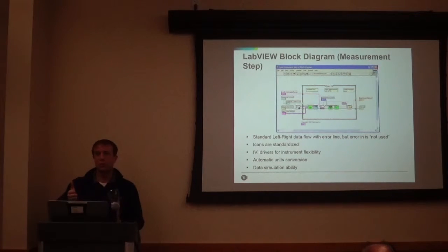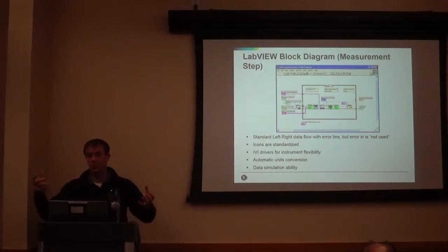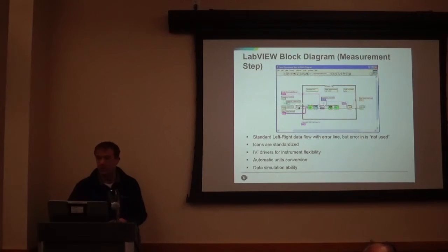Or you have to write a crazy LabVIEW UI that handles that sequencing and reporting and logging and all that stuff, which is hard, because TestStand lets you loop and have variables going on and do a lot of things that if you make your own sequencer, you have to recreate somehow. It's already available and standardized. And you can call subroutines and define your parameters to pass, so you can reuse a lot of sequences.